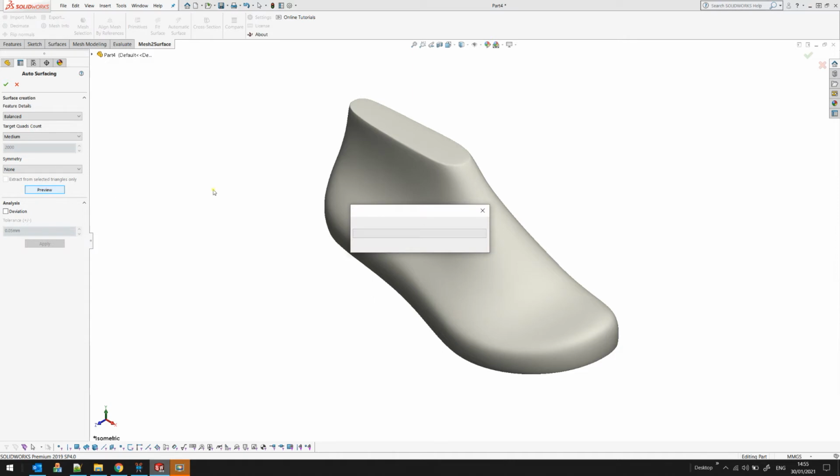You just press preview to see what the result will look like. It takes a while on different objects because the algorithm analyzes the underlying surface. I would like to say that all the meshes must be closed, manifold, not to have holes, in order to get a good result. But every object is different and you can play with the objects by adjusting the parameters here.